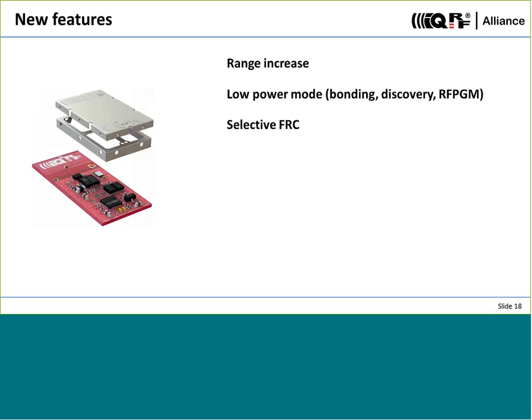So this is why we developed the fast response command. Basically, the fast response command works in the way that it sends a broadcast query, and then the packet is coming back, and each module adds its information into the right space or right point in the packet when it's coming back. So with this, in one communication there and back, you can collect 1 byte from up to 60 nodes.